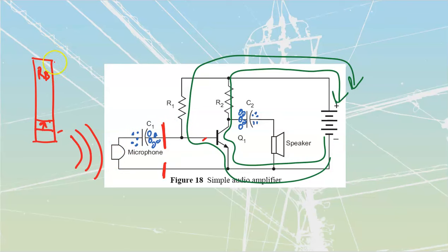When we move that line up, that means that this resistance of the base is going to have fewer volts dropped over top of it. Same value of resistance, it's still a resistor, but it's got fewer volts over top of it, therefore my current is going to go down. I is equal to E over R, right? So if I've got fewer volts over top of the same amount of resistance, I'm going to have less current. If I have less current going through this path over here, what is that going to do on this side? Well, it's going to drop the amount of current that I'm going to have on this side over here as well. If I drop the amount of current that's going through here, that means that I am going to have less voltage drop on this, right?